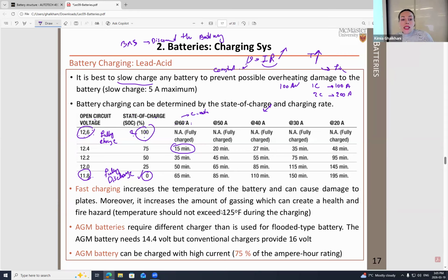We have to say, okay, keep the charge, for example, maybe up to 3.9. It depends on the characteristics of that certain battery. During the charge, if the maximum V is around 3.9, then disconnect it. And for V minimum, for example, if I'm at around 2.4, disconnect it. That's what the battery management system does in order to avoid any risky situation.